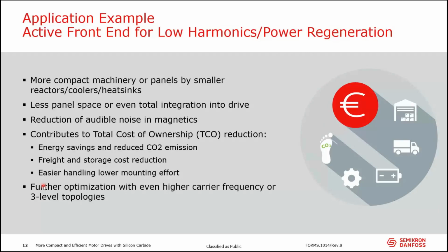But what you see from here is that it's really important to consider the total system when you think about silicon carbide. If you take just the module and put it next to the IGBT module and then compare the prices, you will of course find that the silicon carbide module is more expensive, and that will also remain this way. It will not change soon to be at the same level or be cheaper than the IGBT. But it must not, I think. If you look at the complete system here, then you will easily find that the silicon carbide module brings you so many benefits that it easily outweighs the higher cost.